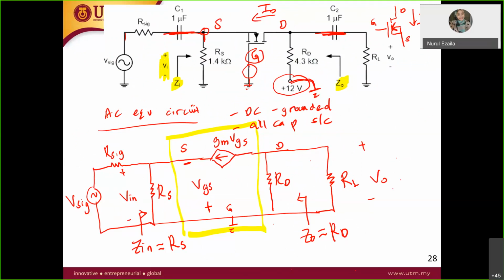So for this one also, we have another resistance. Can you recall a bit on the common base? At the base resistor, if you still remember, 1 over r pi. Same goes to here. We need to find the ZS. So therefore, Z in is parallel with ZS.